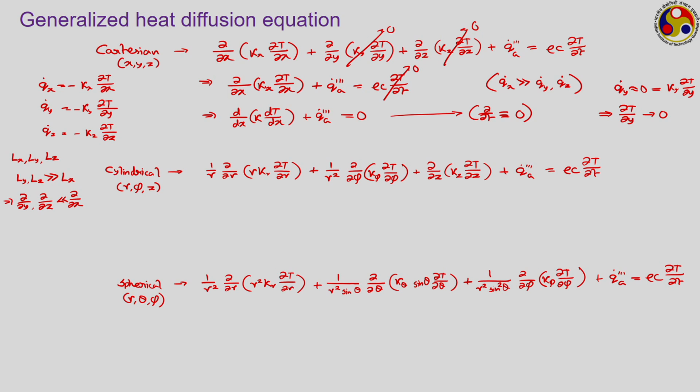And that is the most common situation where we can neglect any variation, particularly temperature in this case, in the y and z direction. So, the temperature gradient in the x direction becomes the only important one to us, and accordingly heat conduction in the x direction is the one that we have to consider in detail. A very common example, just look at the wall of the room where you are sitting. Just think about the wall.